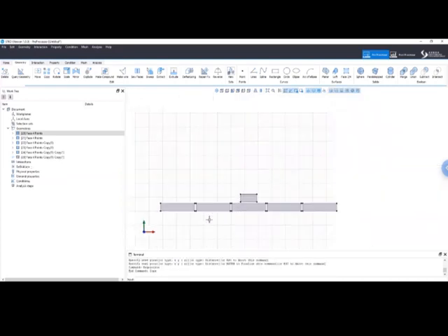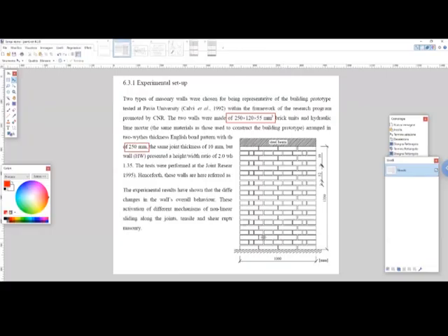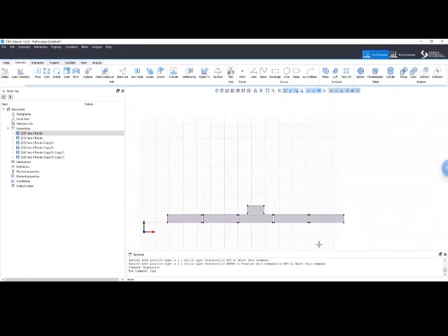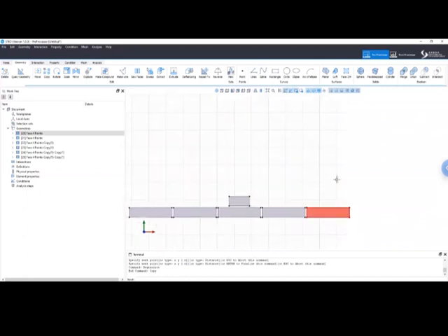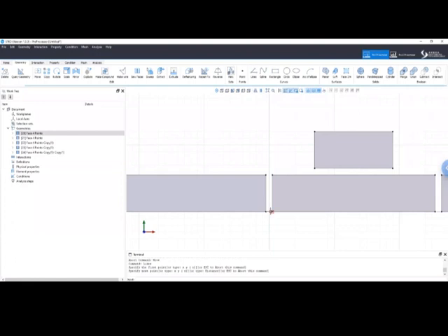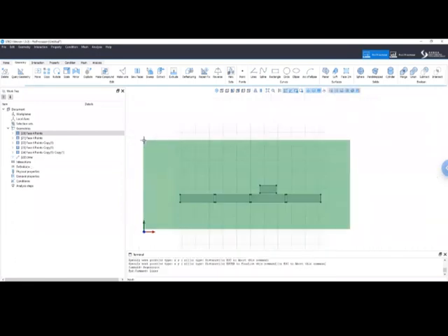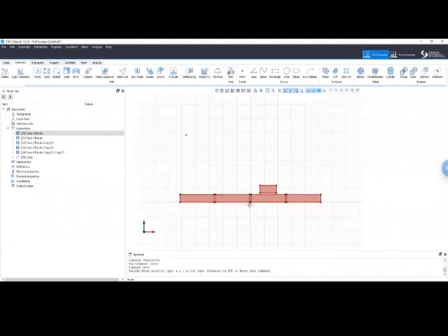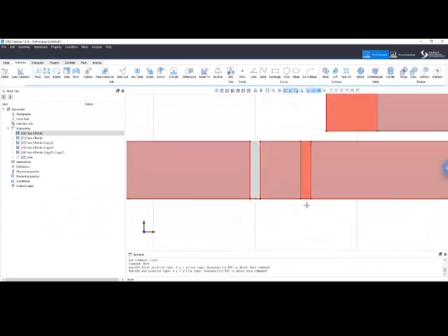So now, as you can see, they are slightly more. Let me see how many of them we have. Actually, we only need 4 of them. Yes, 4 of them. So let me remove this one. Now let me center everything. So let me create a line here. I want to put everything in the center. So let's take everything, move, and then move this one at the 0, 0, 0 coordinates of the center.